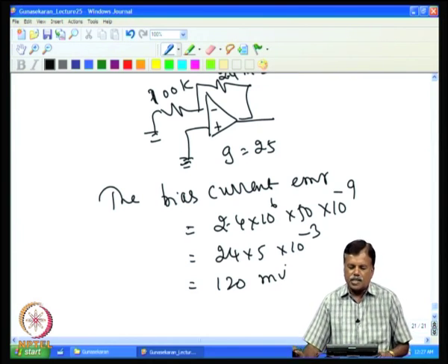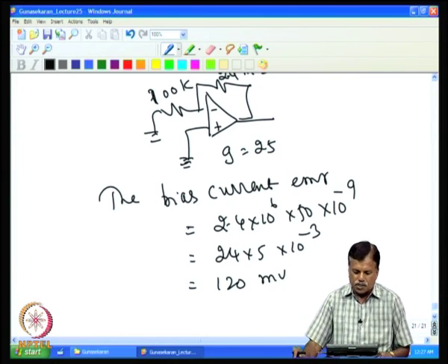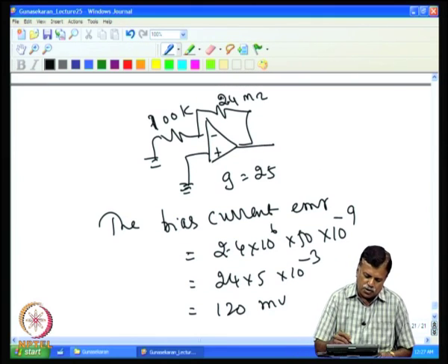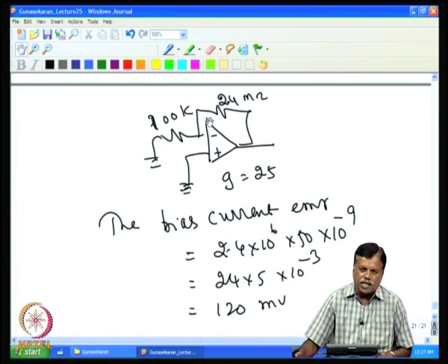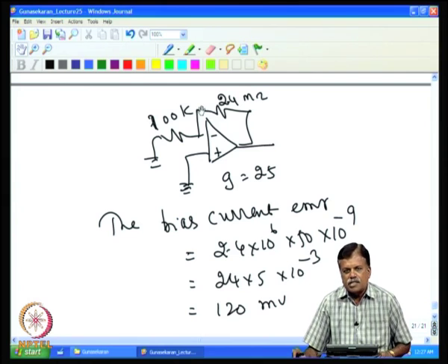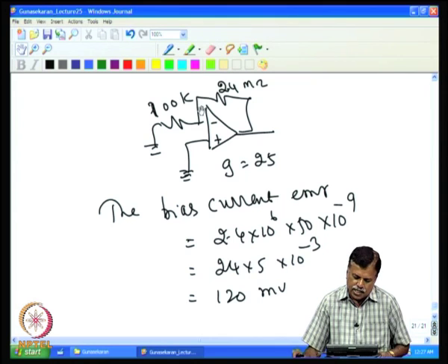So the bias current error becomes larger as soon as you increase the resistance value. If I want to set the gain, I should not put in any resistance I like. The higher the resistance at the feedback, the higher the error. This error is irrespective of the offset voltage and offset voltage drift; it is coming purely because of the bias current.